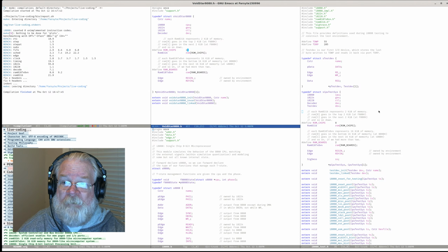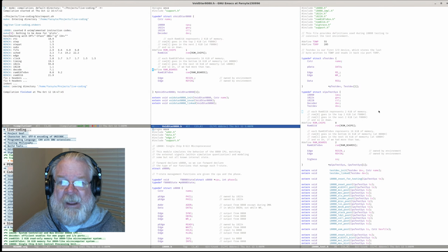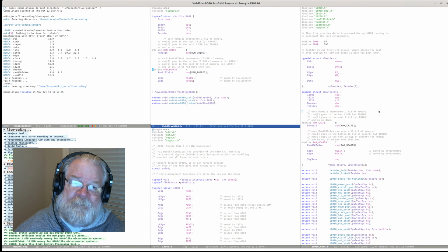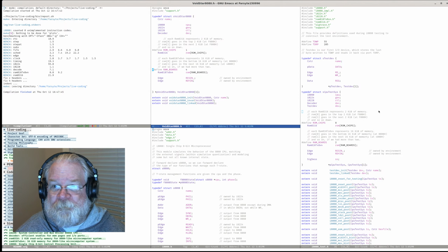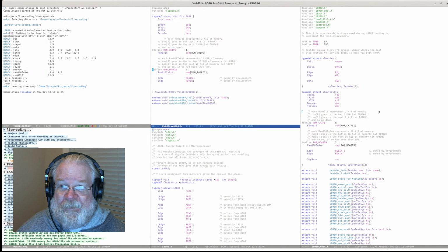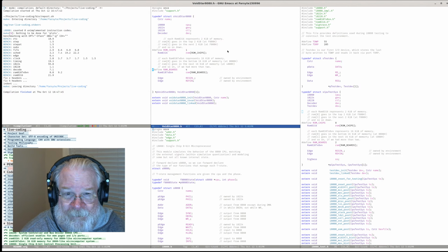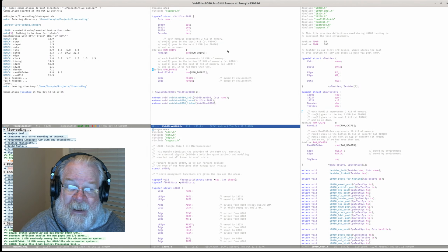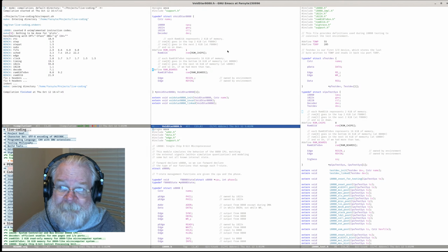Now, ROM chips, I only have one ROM chip. I have 4 RAM boards. Now, this means that I'm going to do something that I have seen in systems at the time, which is we had a RAM board that was 16K, taking up the last 16K, but we also had a ROM taking up the last 2K. So in that instance, we're actually going to waste 2 kilobytes of RAM, which will never be visible because the ROM is going to be there. Now, maybe there will be something we can do in our VoidStar that says, rather than the normal shadow, so shadow takes our ROM and maps it in at 0, and then it snaps back out at its normal address. Perhaps we'll have a thing in the future that says, okay, we can get rid of the ROM and expose the RAM that was behind it. Kind of cool.